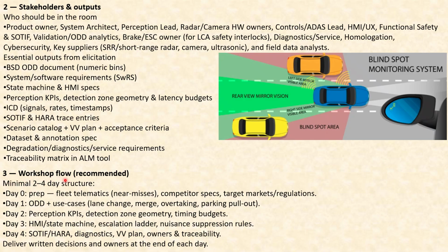Now, talking about this recommended workflow, usually this takes a 2 to 4 day structure. Day 0, this is a sample thing which I'm offering to you so that you can implement when you are developing this blind spot monitoring or blind spot detection: fleet telematics, near misses, competitor specifications, target market regulations. Day 1, ODD plus use cases. Day 2, perception KPIs, detection zone geometry, timing budgets.